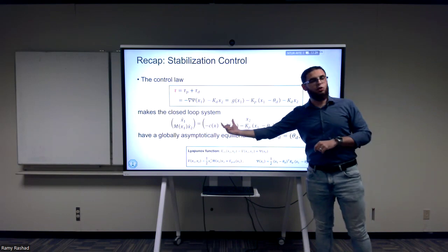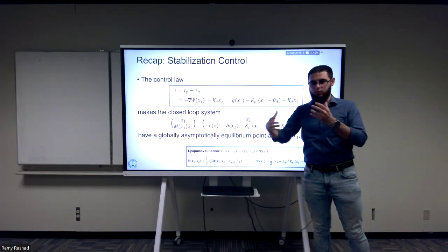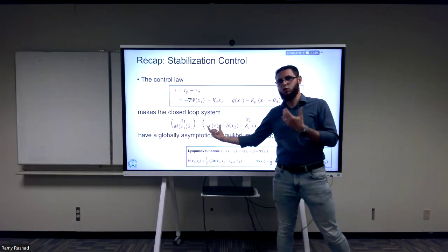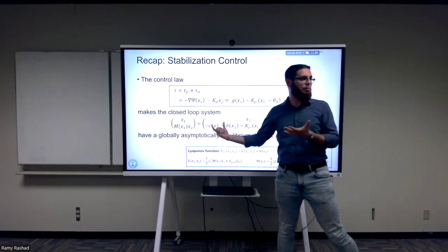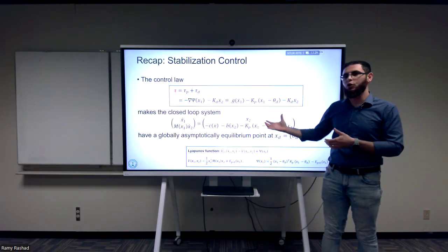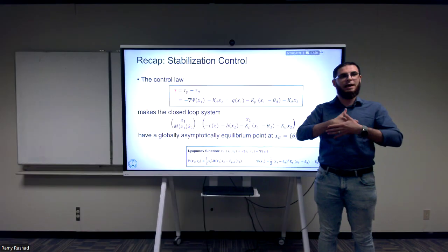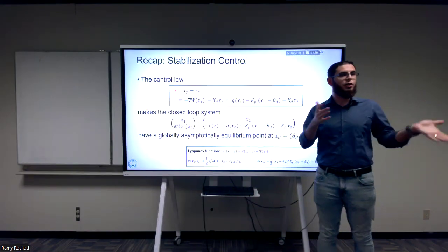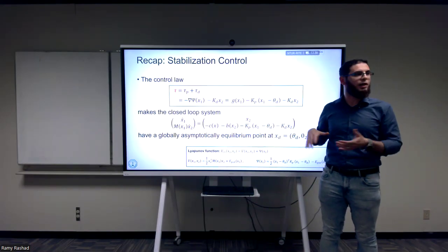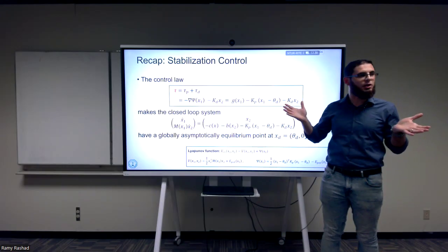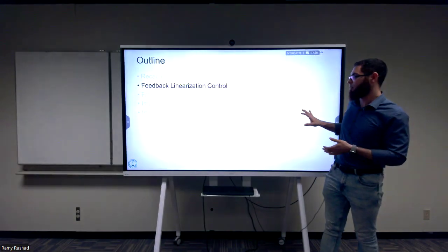So this skew-symmetric term, C is part of the M dot minus 2C. You see, it's also a good nonlinearity. Skew-symmetric terms in the Lyapunov analysis mean that there is no energy neither created nor destroyed. It's just some routing of the energy going back and forth. That's why it just disappears from the energy balance when we calculate it.